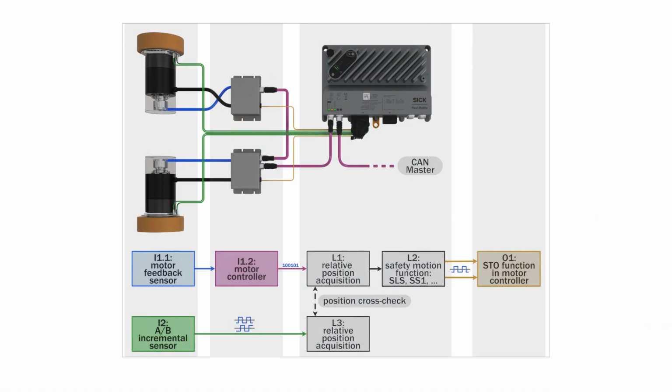The CAN Listen mode of the CAN gateway enables the safety controller to receive the process data without being an active CANopen device. It only listens to an existing CAN communication. A typical application is the reception of movement data within a dual-channel architecture.